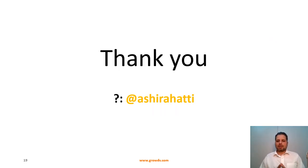This concludes part 1 of bootstrapping, wherein what we have established so far is that we have understood the DUT. We had figured out that we need to know about the DUT from 3 points of view. First, what is the interface, so that we can connect the DUT to our test bench. Second, what is the software view of it, so that we can program the DUT. For the UART DUT, both the data path as well as the control path are accessible through the APB. And the third was the protocol view. For the protocol view, we have only looked at it briefly. We have not covered the UART protocol exhaustively, but we have explained enough to make sense of the test bench exploration that we intend to do.